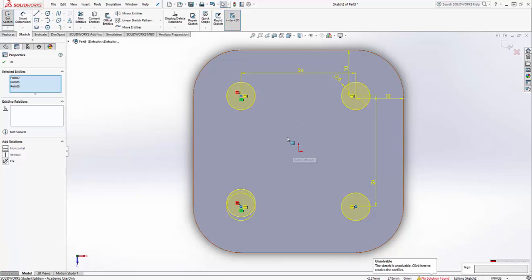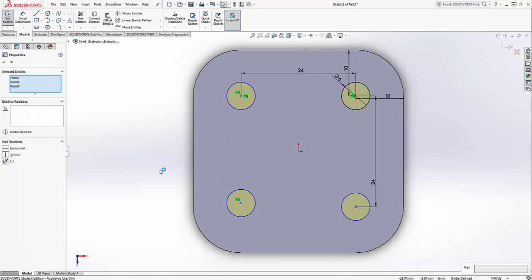Okay. Here's another issue that we just ran into. It's saying that the sketch is overdefined. So what that means is when you did either dimension or a constraint, I'm just going to undo to make it go away. It can't resolve it. What you've already given it conflicts with what you're trying to give it. And in this case, we're saying that this point and this point are all trying to be horizontal. And that's because I forgot to deselect this point. So you can either control select the point there, or it'll be in the list that you can find it and unselect it. So I'm going to say that those 2 are horizontal, and now it's not a problem.